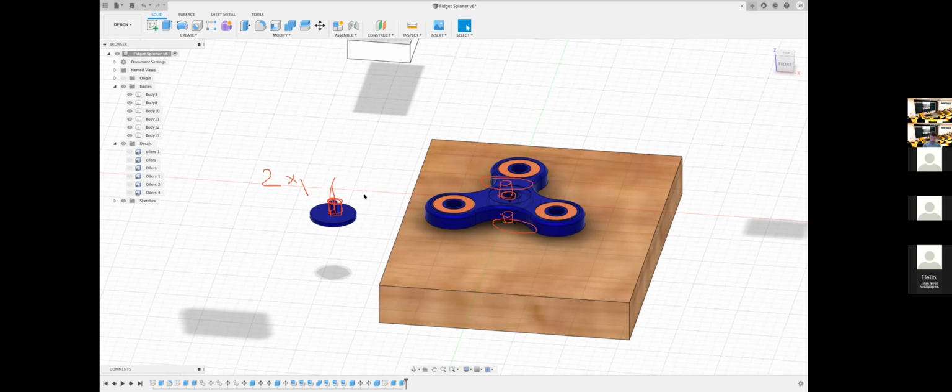And in the slicer, basically, you're telling it the printer size, the feed rates, the nozzle diameter, the temperature at which to print for the material that's being used, all those things that are designed for a specific printer. So for print shops, all you have to do is send them an STL file. STL is universal, and everybody can open it up, and then they will slice it for you.